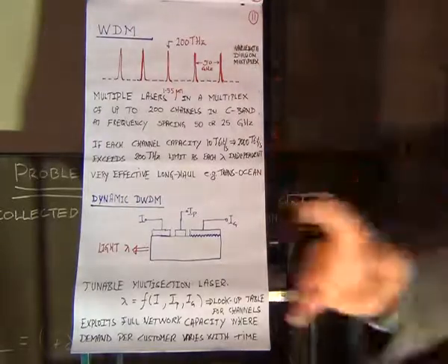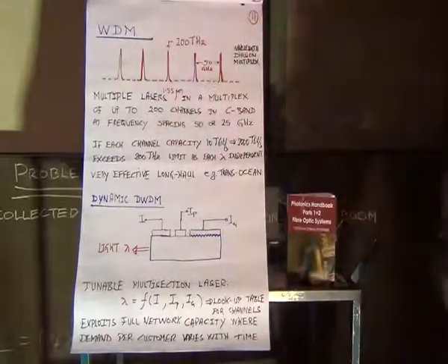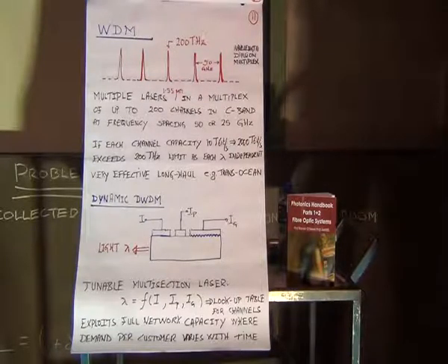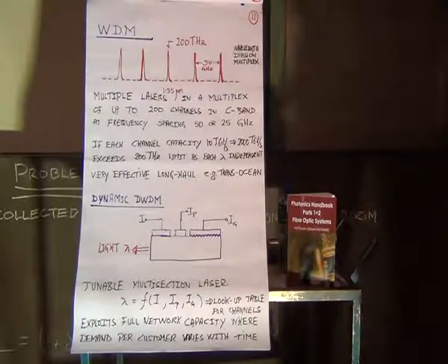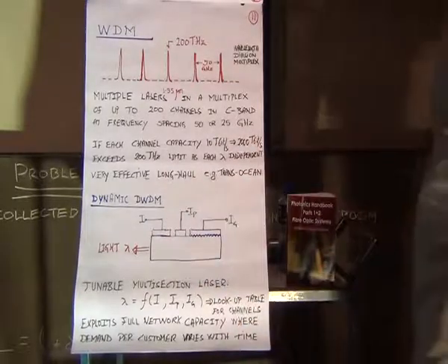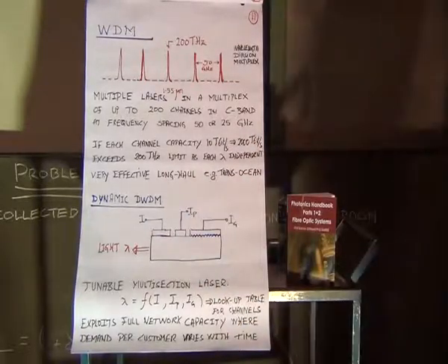So you have a way to separate out the channels. You could arrive from Dublin to Cork, where there's a spur out to the transatlantic optical cables, and you could transmit the New York bound channels and reflect passively with a fibre Bragg grating the Cork bound channels. Okay? You could furthermore use the wavelength as the address of an IP packet.